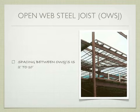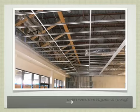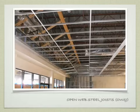The spacing between open web steel joists, so in terms of the density that they're put together, is somewhere between 2 feet and 10 feet. And that's going to be determined based on the load that's up top. Right? So whatever you're trying to support is going to determine the density of how closely spaced these open web steel joists are going to be. So if we look up here, don't look at the first bit, because that's the false ceiling. They're going to put those little funny ceiling tiles like this in. But we're going to go up a little higher, and we'll see the open web steel joists there as well.